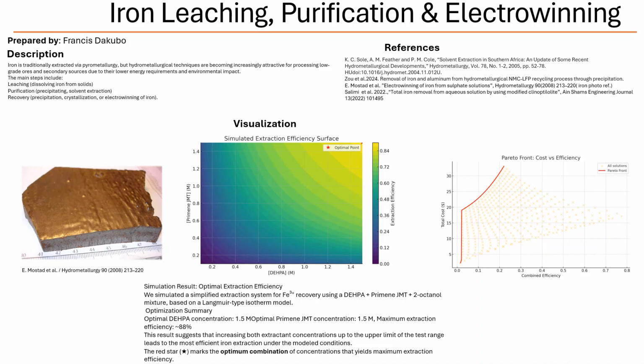The evaluation mechanism, you said, it looks at trends in ion concentrations. Yes, both the trends at the switching points between those time segments and the overall trends in the last reactor. Why are the trends so important? Because they tell you about the stability of the process. If the concentrations are bouncing all over the place, that's not good, even if the final values are within the acceptable range. You want a smooth and predictable process.